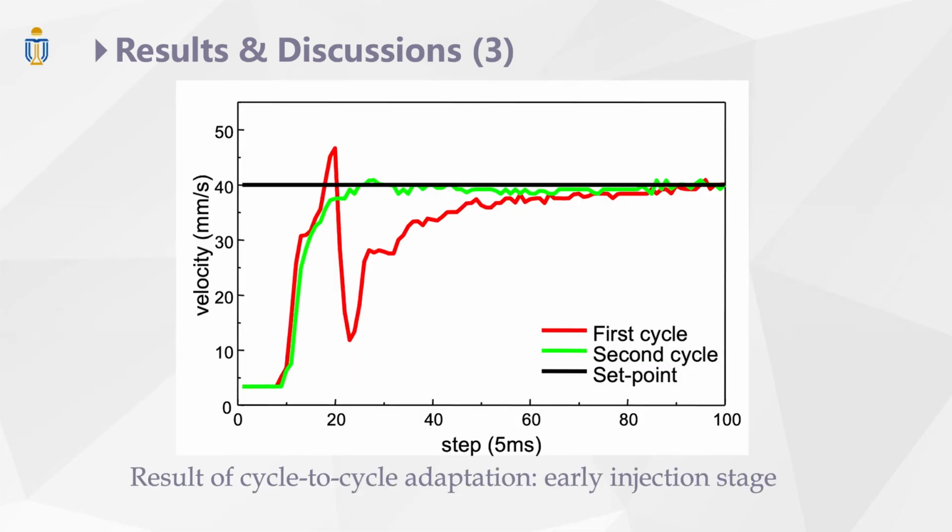With adaptive control, you need to start with an initial model. The model is then updated, and the control performance can improve with time. We can also introduce cycle-to-cycle or batch-to-batch learning. We can update the initial model from the end of the last batch's dynamics. If we do that, the control performance in the early stage of the phases can also improve dramatically.